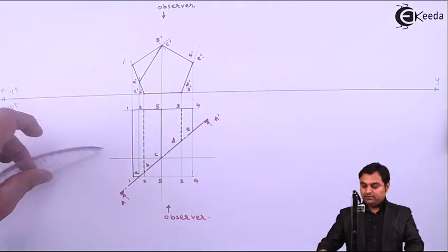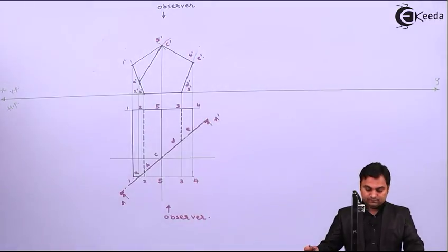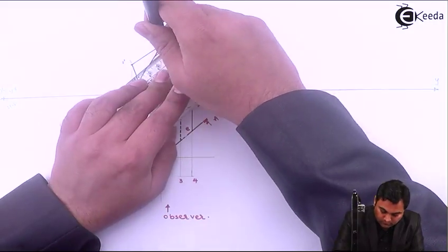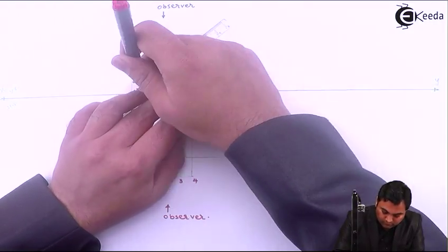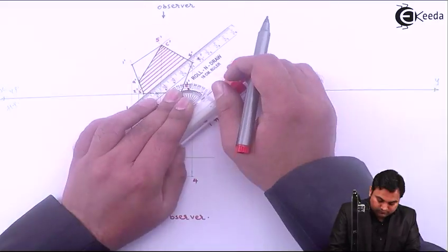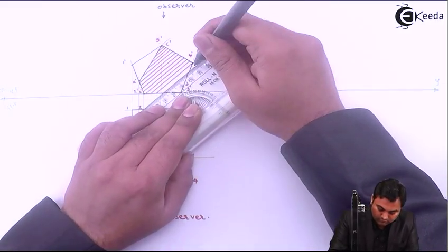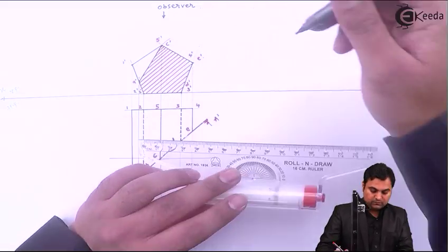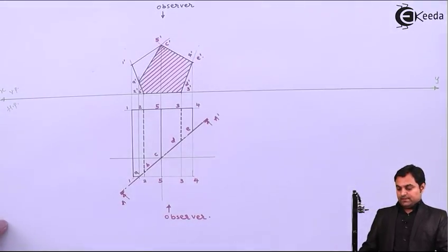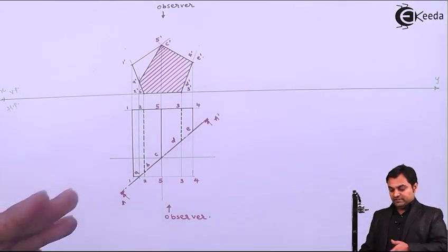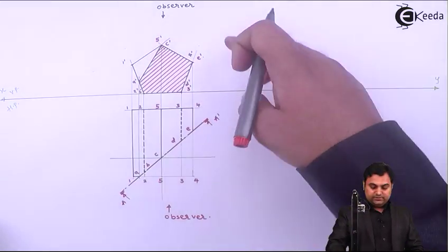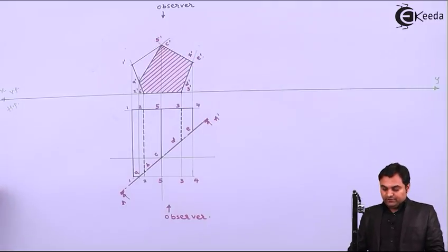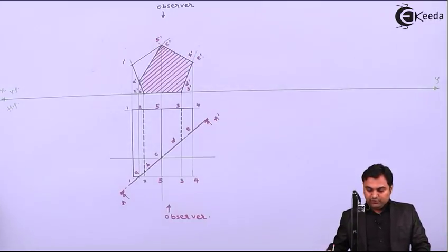Measuring 45-degree angle. So this is the sectional front view. It means when the pentagonal prism is cut in this way, then here we are going to get the sectional front view. Next, I'll plot the sectional side view, and for that we would be looking